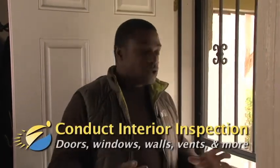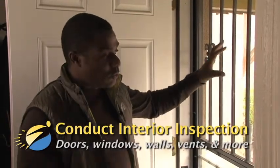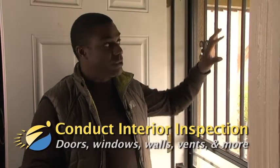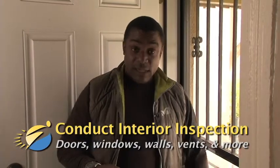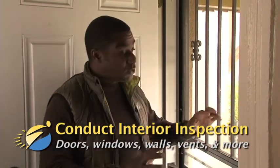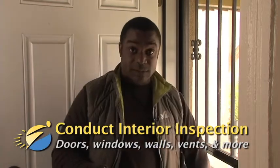So we're going to start the interior inspection section of our audit. That starts right here at the front door with this storm door. When we take a look at this storm door, right now it's set up in summer condition. It's got the screen at the top and the glass at the bottom. And that's fine if we're in the middle of summer. But if we're in the middle of winter, we want to make sure that this storm door is set up in winter condition with glass above and glass below.